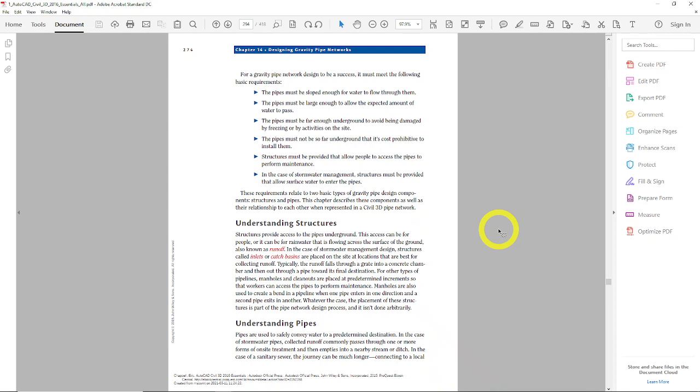They need to be at not too steep of slopes sometimes, depending on the design needs, and not too shallow of slopes, which is even more critical, so things actually flow. One thing I've run into with some subdivisions is not making pipes have a high enough minimum slope. If it's too close to zero for gravity, sometimes the contractor or other unforeseen things make it hard to maintain that slope when it gets built. So the slope of the pipes is very critical.